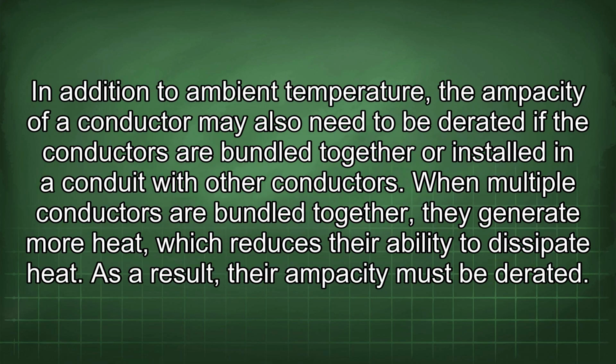In addition to ambient temperature, the ampacity of a conductor may also need to be derated if the conductors are bundled together or installed in a conduit with other conductors. When multiple conductors are bundled together, they generate more heat, which reduces their ability to dissipate heat. As a result, their ampacity must be derated.